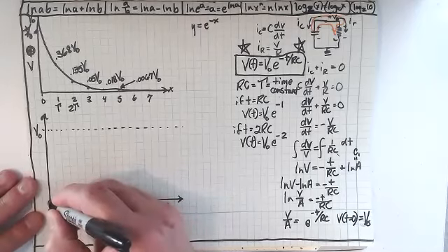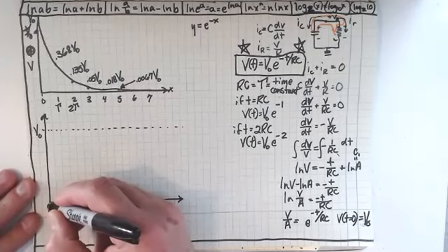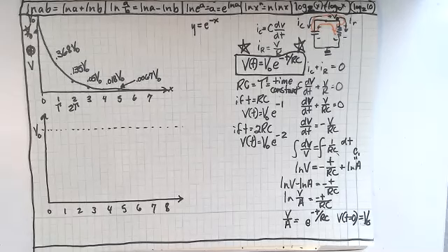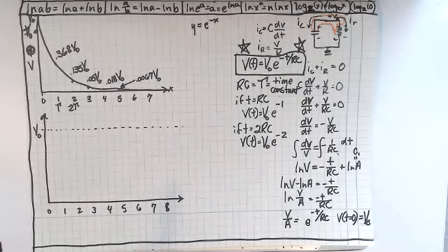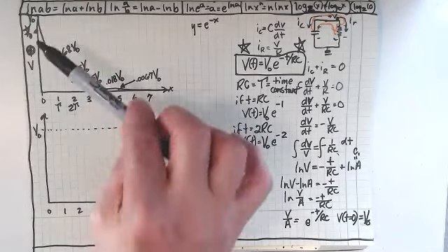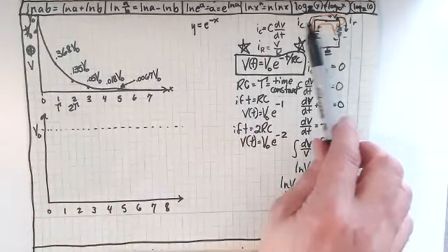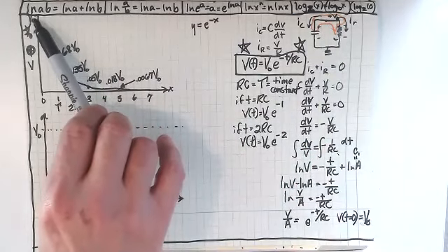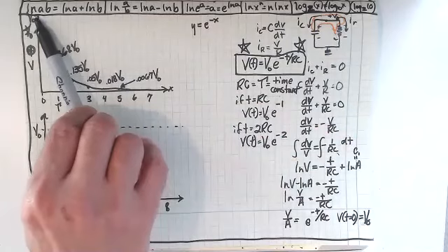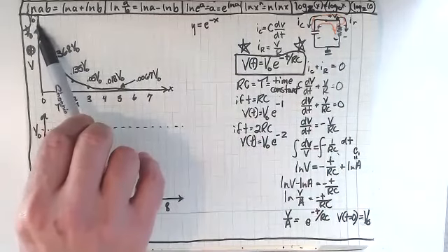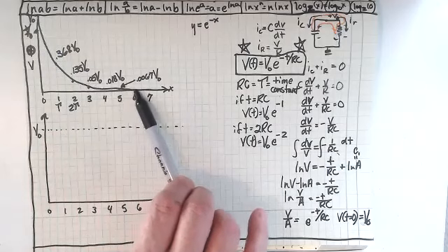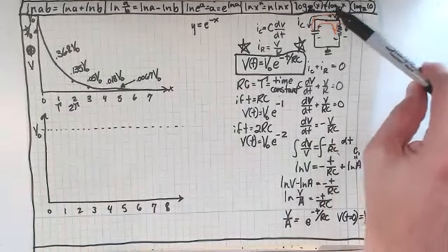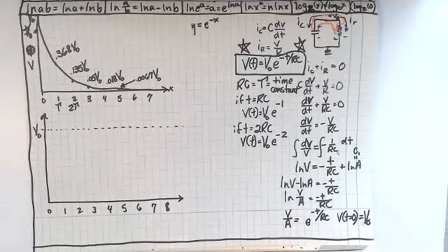So when we start to charge a capacitor, and really what am I looking at as far as the V0, right? This is really saying that once I have that voltage source out of here, the voltage on the capacitor is going to leak out like this. It's going to leak out of the capacitor through the resistor to ground. That's what it's really saying.